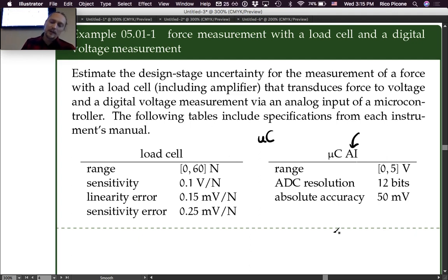Something that happens when we start doing control is that your control output is tied to some control law, which depends on the measurement. Sometimes you're going to measure something and you're way off in your error, so you want to put out a large control actuation force. Say you're trying to balance something, and it's getting way off, and you want to put out a huge force to counteract that. Well, maybe your actuator doesn't actually have the ability to put that much out. So that's also called saturating. It's saturating your actuator. And so it happens a lot.